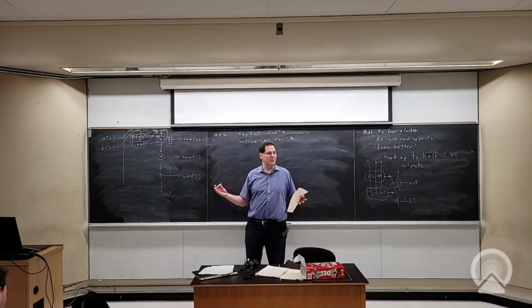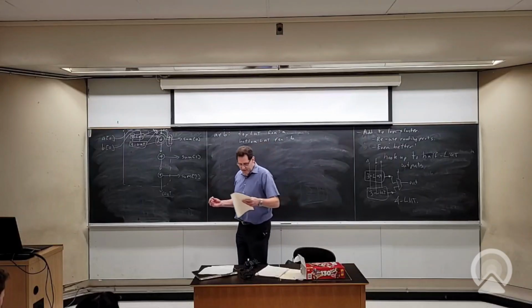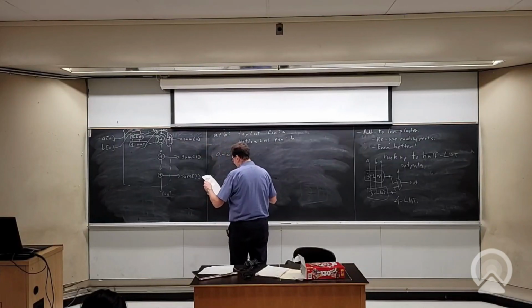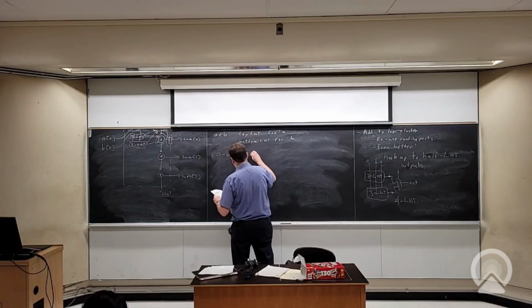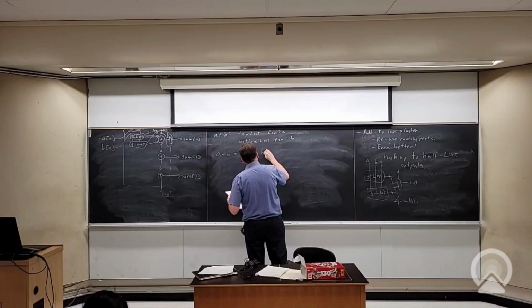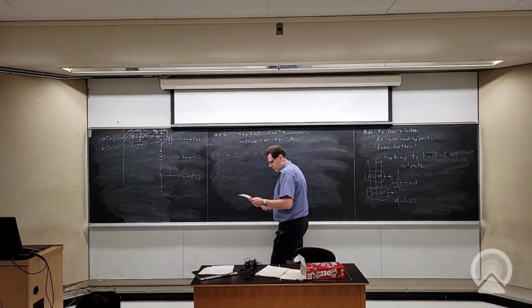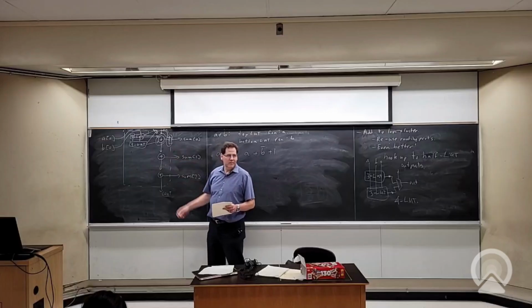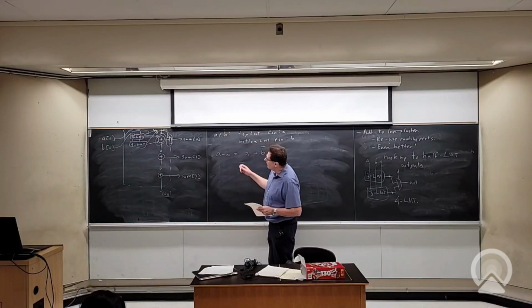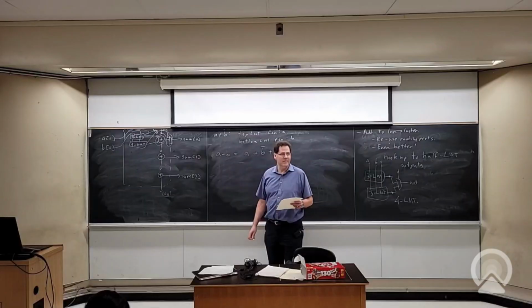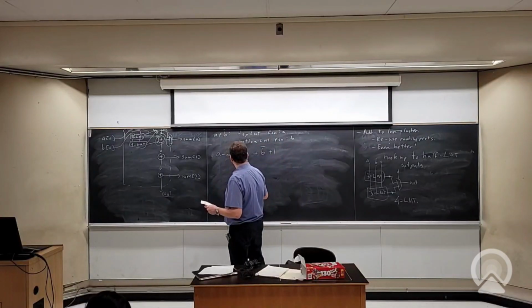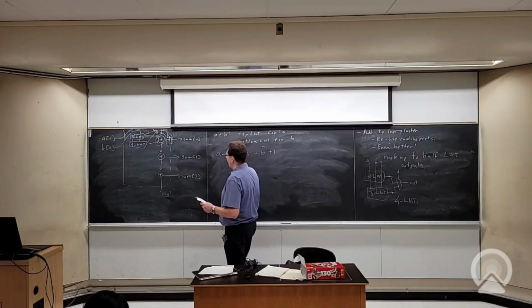Okay, so it worked, right, for a basic adder. I mean, the LUT didn't add much value there, but it didn't get in the way. Let's say I want to do a subtractor. Say I want to do A minus B. Okay, so we do that as A plus B bar plus 1 in 2's complement. How do I make this work in this structure? So what do I put in? I'm doing A minus B. What's the top function? So top LUT is A, right?